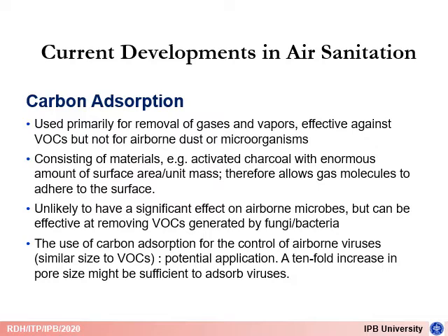The system consists of materials, for example, activated charcoal with enormous amount of surface area, therefore allowing gas molecules to adhere to the surface. It is unlikely to have a significant effect on airborne microbes, but can be effective at removing VOCs generated by fungi and bacteria. The use of carbon adsorption for the control of airborne viruses, which is similar to VOCs, is a potential application. A tenfold increase in pore size might be sufficient to adsorb viruses.